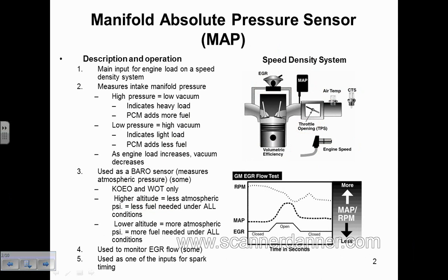in its memory. So if you're looking at the scan tool, you might see MAP volts and BARO volts on the scan tool, and they're 2 separate data parameters. You turn the key on, let's say you're dealing with an analog type MAP, and this is pretty typical, key on, engine off, MAP voltage 4.5 volts. Of course, it would depend on the car you're working on. And then you'll also see on the scan tool that they give you a BARO voltage too.